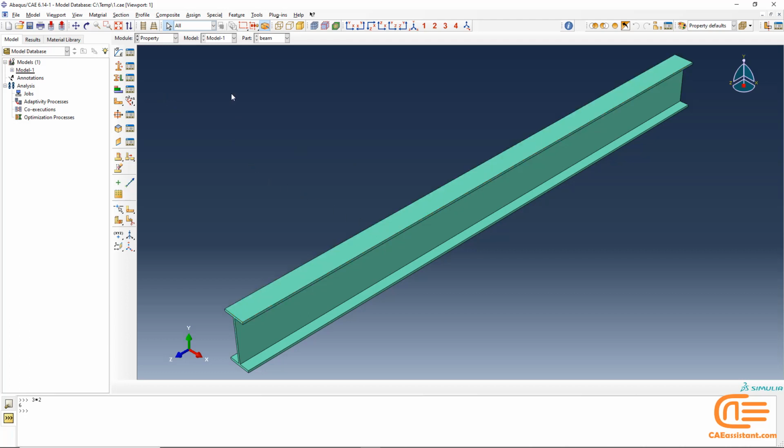This method of material allocation in Abaqus allows you to assign different materials to different regions of a part. Suppose this beam has a material from the tip of the beam to the middle and another material for the rest of it. You can easily assign these materials by partitioning it, which I will show later. Well, a lot of things can be done in the property module, such as defining composites, beam sections, and more. But for this simulation, we are done with this module.